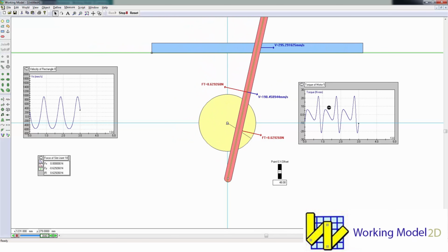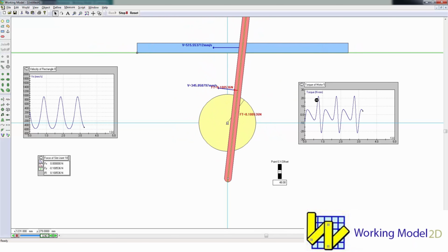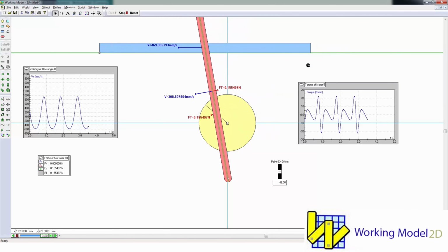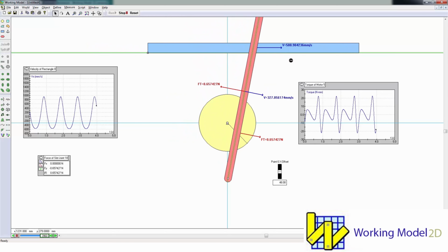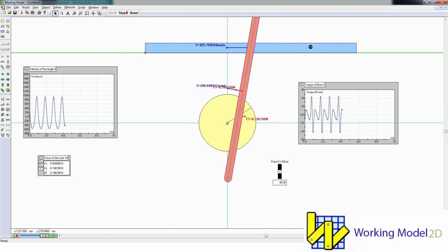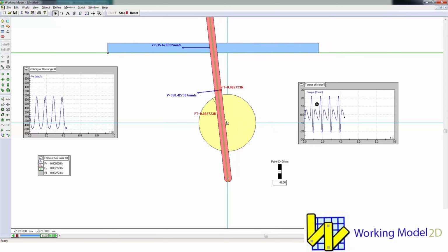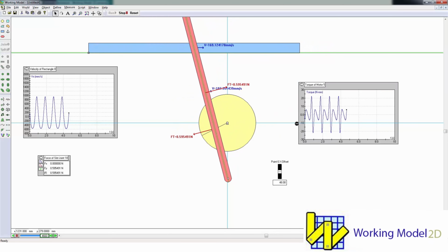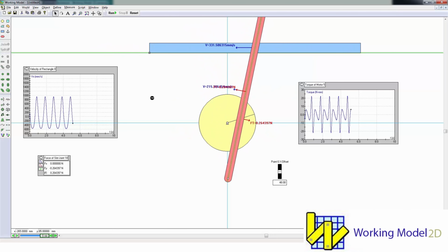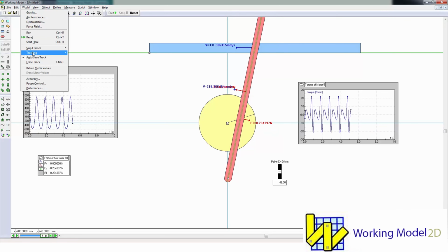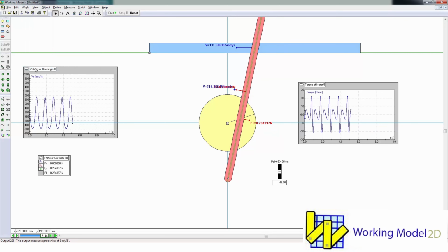and read it back in, we could drive the motor using this data. And then because we'd be driving it with a torque rather than a velocity, you know that other forces can overcome other forces. So if we put a heavy load on this, we're certainly going to affect the ability to maintain that constant speed using this profile. So this is good. We can investigate different things. Let's stop this now and let's click on World, and we'll choose Retain Meter Values.